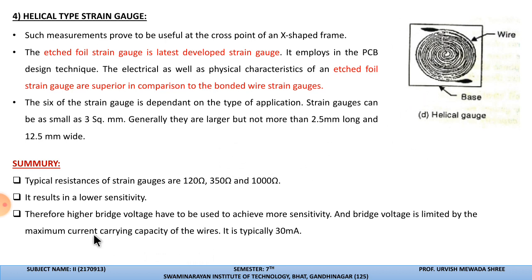If we want to use these strain gauges for higher sensitivity, we need to apply more voltage. In the bridge circuit, voltage is limited by the maximum current carrying capacity of the wire.